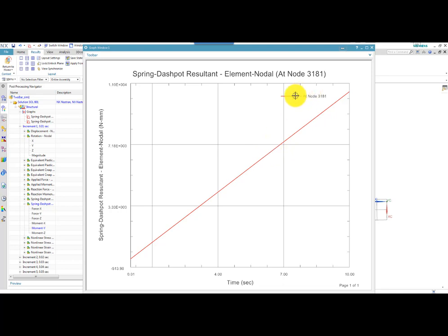And that proves the big difference. So now you see that when you use a follower load, that will have an effect on the tangential stiffness. You will actually add some kind of a follower stiffness to the system, which has to be included for large displacements. So that concludes my presentation of nonlinear geometry.